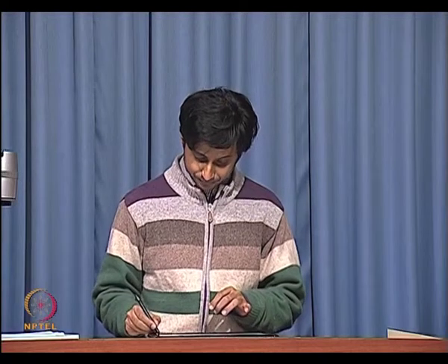All right. Now, all that I need to understand is how much is the power delivered to the load, and depending upon the amount of power delivered to the load, I will be able to understand what is the efficiency of this particular amplifier. By the way, the amount of power delivered to the load at the desired frequency. Do you agree? At the desired frequency. At other frequencies, it really does not matter what power is delivered to the load, because we do not want it anyway. So, at the desired frequency, what is the power delivered to the load? That is going to give me an understanding of what is the efficiency of this particular circuit.